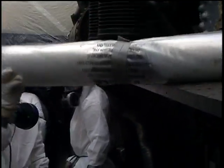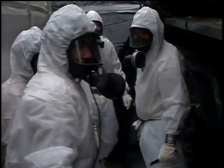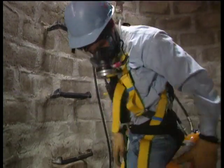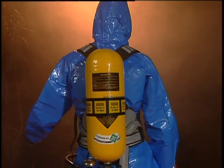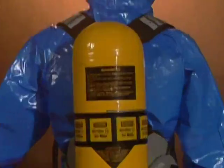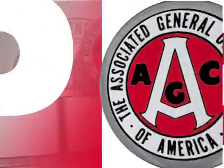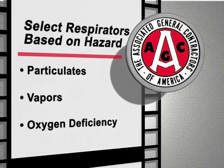A respirator is a protective face piece, hood, or helmet that is designed to protect the wearer against a variety of harmful airborne agents. There are three main types of respirators: supplied air respirators, which provide pressurized breathing air; self-contained units that have air in a tank that you carry on your back; and air purifying respirators that use filters to clean the air you breathe. Select respirators based on the hazard to which you will be exposed. These hazards include particulates, vapors, oxygen deficiency, or a combination of hazards.